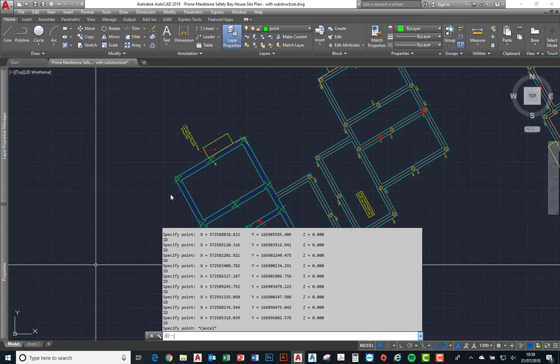So it's not showing all of my points, which is important to remember when you export the last 10 of your commands so that you're not missing one. In fact, cancel comes up as a command, so it only really shows you the last 9, and that's why you'll be missing some if you don't do it in small sections. So it might be worth doing 6 there and then the next 6 for the next section down.